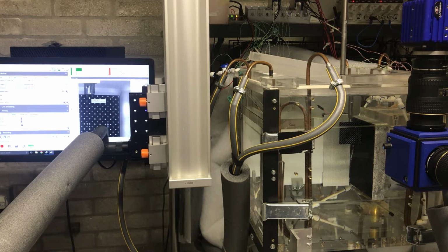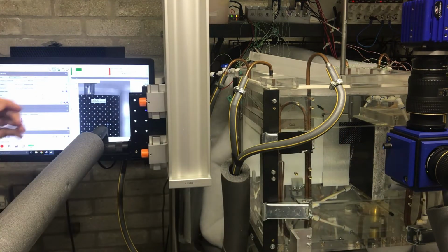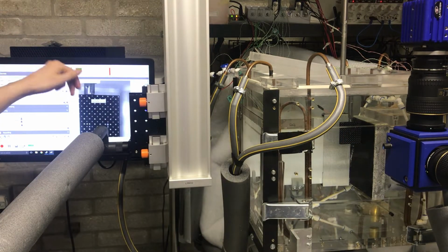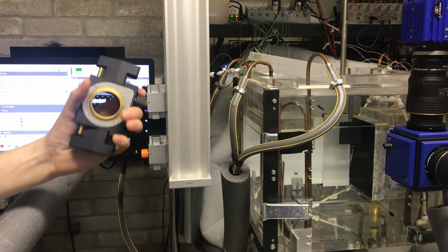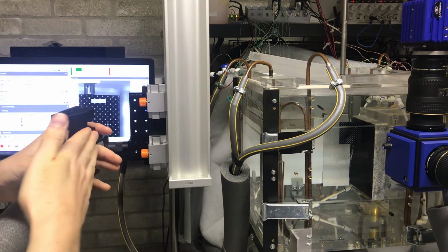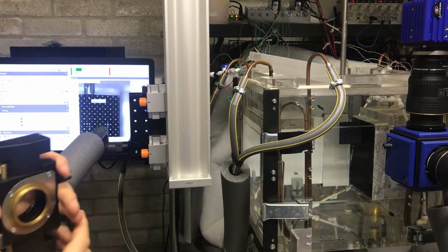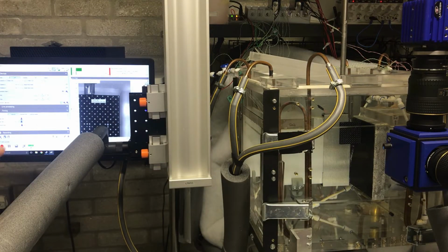If you're looking at a particularly oblique angle, or if you're not looking straight on, you might find that one part of the target is in focus and the other part isn't. And that's where you could use something like this, which is a Scheimpflug adapter, and that enables the lens to be slightly rotated with respect to the camera. This would fit in between the camera and the lens, and enables you to bring into focus something that is not in the same plane, or not coplanar, with the imaging sensor. But that isn't necessary in this particular case.